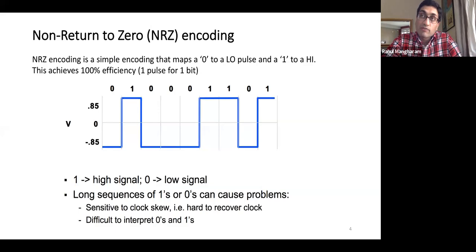So for every byte of data, you essentially have 2 additional bits. So you know the format of the data and you know the speed of the data. As soon as I start sending it to you, you say, okay, the first bit was a start bit, now the second through ninth bits are the data bits, and then there's a stop bit. And I know the rate at which the bits are coming to me.